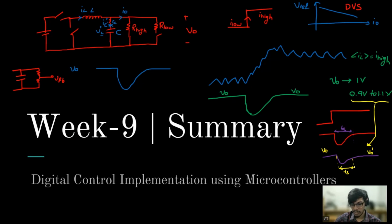Also, my transient response is improved because I'm deliberately reducing the voltage so that it does not have to come back to the previous voltage, which will take a lot of time. The idea is that we dynamically change the voltage with respect to I0. They will have some gain, say G or minus R. At a particular load, at I naught equal to 0, the value is V reference naught.